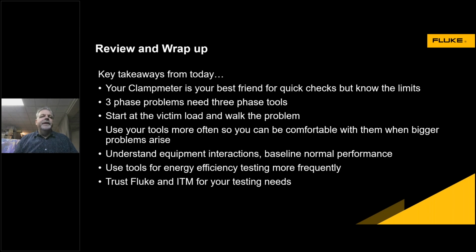Use those tools for energy efficiency testing more frequently. They typically all have that capability. The trick is trying to find time to do that, but if you let them log for you, you can get an idea that, hey, I'm having a power factor problem at 2 o'clock in the morning. Why is that happening? Is it something I should be concerned about? Am I incurring penalties because of that? What can I do to fix that? Those are the kinds of things you can test for.